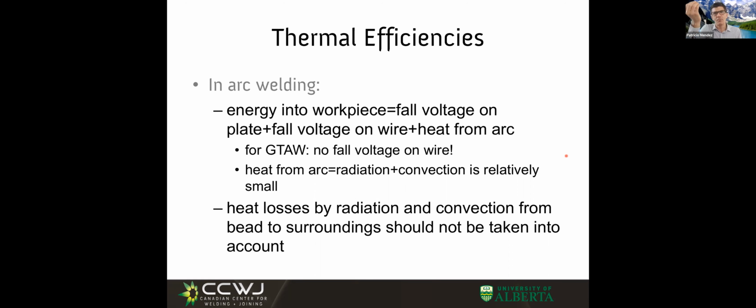And then when the droplet falls into the weld pool, in this set of notes, well, I need to update, but not 100% of the heat of the droplet goes into the weld pool. Why? Because we have some spatter, right? And the spatter that takes away mass takes some energy away with it. But the spatter is not that big. So we can say the energy of the droplet is also part of the weld, right?